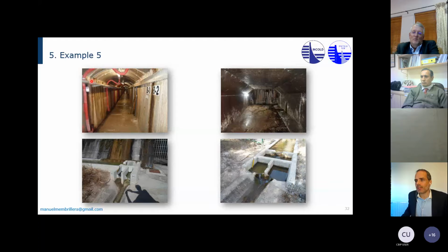So one problem we have here is this is not the RCC concrete. This is like a precast concrete that is really covering the real concrete of the dam. So it's very difficult for us to carry out visual inspection here, because even the joint meters, so this is block 0 and this is block 2, the joint meters are not all the way trustworthy.